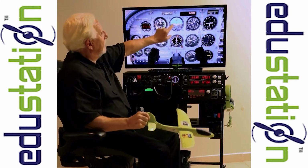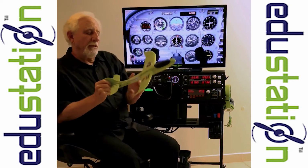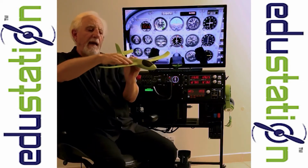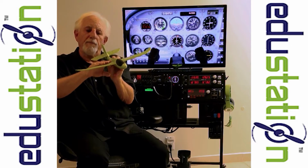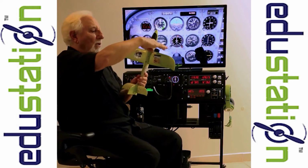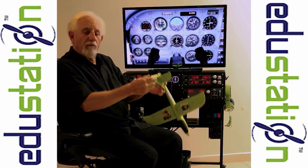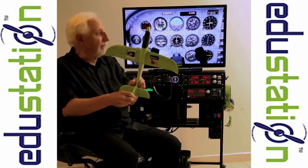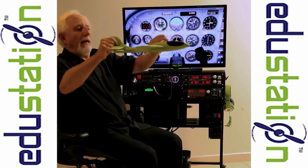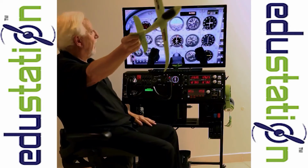We want to pay attention to this because we do not want to go up steeper than 20 degrees up. The reason is that in order to fly, we need to have lift, and lift is generated by attached air coming over the top of the wing. If we put the plane in too steep of an angle of attack, that air no longer stays attached to the wing, and you get a stall, and the plane will fall. There's no flying without lift. So we want to watch this. The calibration on the top is roll angle, 10, 20, 30 degrees left, 10, 20, 30 degrees right.